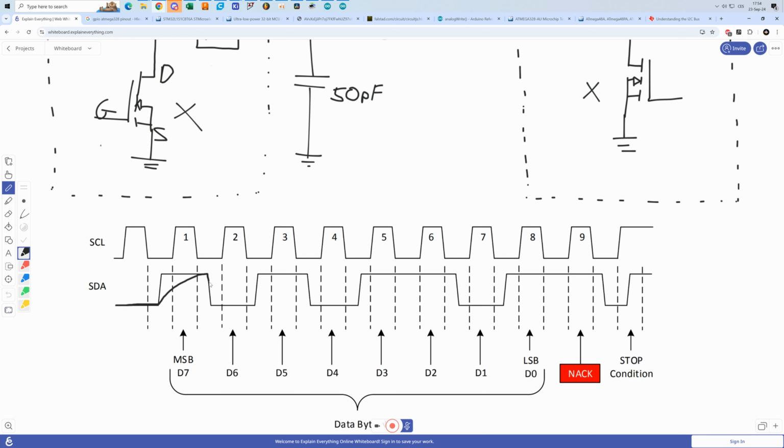And of course, it will have a fast falling edge because the falling edge is triggered by the transistors. Now again, when the bus is pulled high, it's going to be pulled by the resistor, which is slow. This is an extreme case, of course, but it's not that far from reality when you deal with very high transmission speeds. It takes some time for the resistor to charge the capacitor.